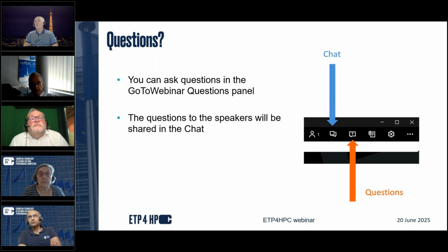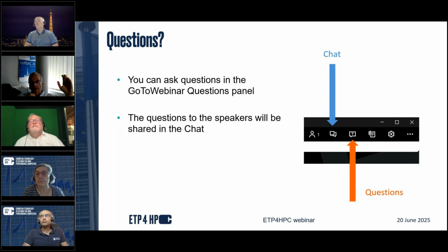I think also in terms of technology, you will see more and more hybridization of various technology. So we already have systems which have HBM on DDR, but you see the memory is a full hierarchy from the non-volatile memory to the very fast SRAM. So here, the boundary between where SRAM is better, where dynamic memory is better, is evolving with the new technology.